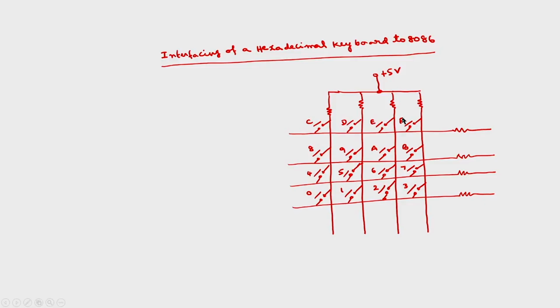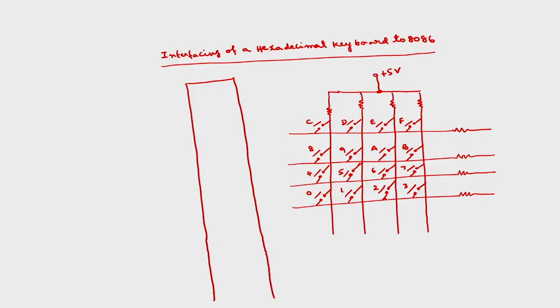This has to be connected to the ports of 8255. So I am taking 8255 here. It is 8255. This will be connected to the 8086 this side. I am not showing these connections, which we have already discussed in the earlier classes. To one of the ports of this, you have to connect through diodes. This you have to connect to one port.